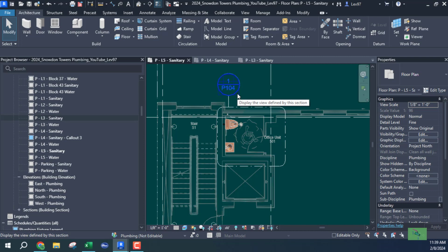We're going to call out plans that are similar where we don't have to use the same technique that we used in AutoCAD, where we're just using lines, and it's not going to affect the entire model. But in Revit, if we use piping, it's going to show in all of those particular similar views.